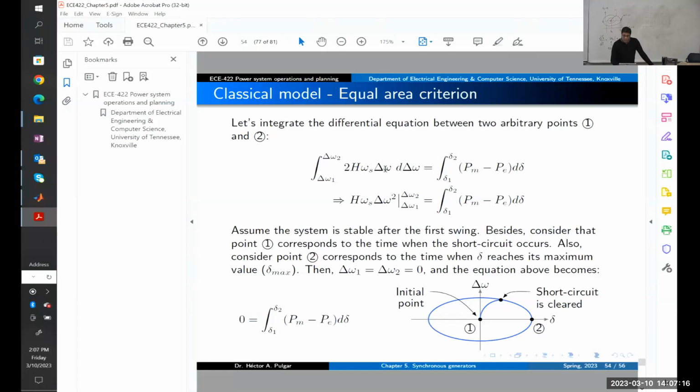This delta omega here, you just have one variable, so the integral of this will be delta omega squared over 2. That 1/2 gets canceled with this 2 here, and the result of that integral is nothing else than this. But this needs to be evaluated between those 2 points. On this side, as we have electrical power, and the electrical power depends on the angle, we don't know yet what is the result of that integral.